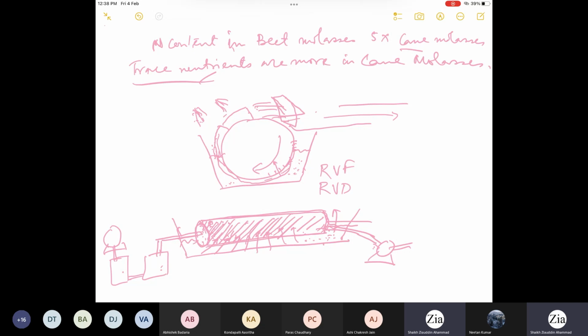When one cycle of this drum completes, the initial surface area will automatically be renewed. So instead of operating in batch mode, you can run it in continuous mode to filter the liquid and separate the solid. This is one mechanism to get a continuous operation of solid separation.